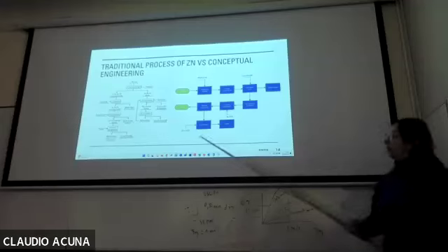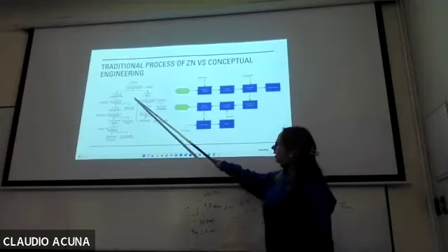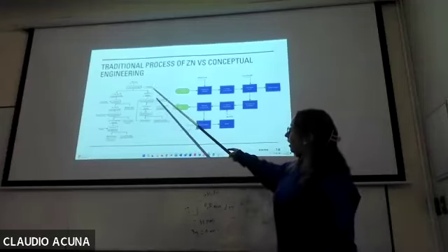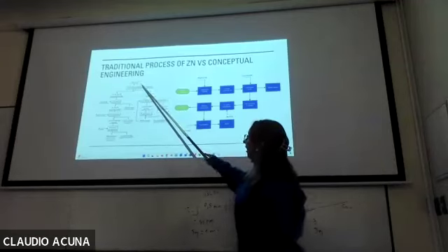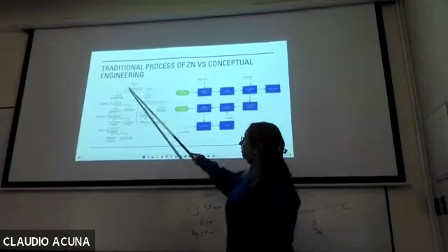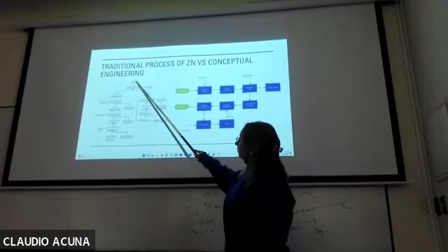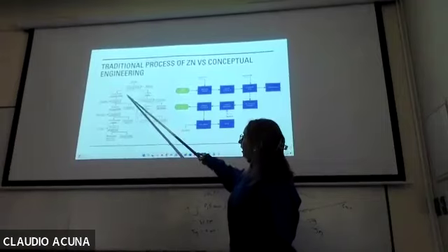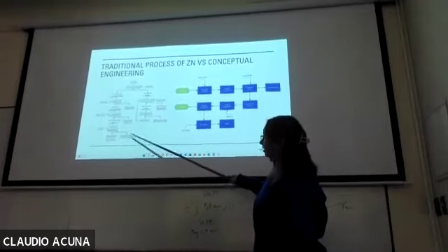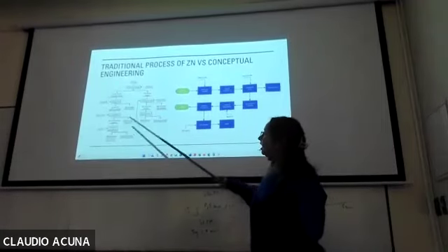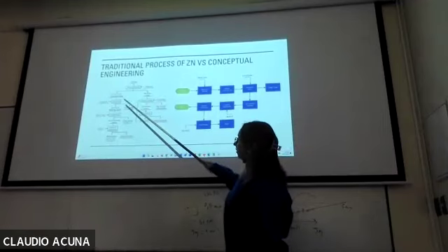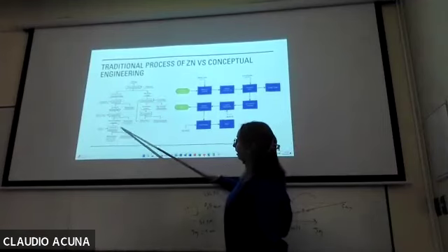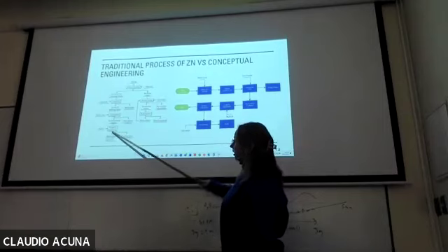Okay, the traditional process is on the left side. We have the CSFD dust, and with waste acid we leach this material. Then we have the cementation, precipitation of arsenic, and then the zinc and cadmium precipitation.